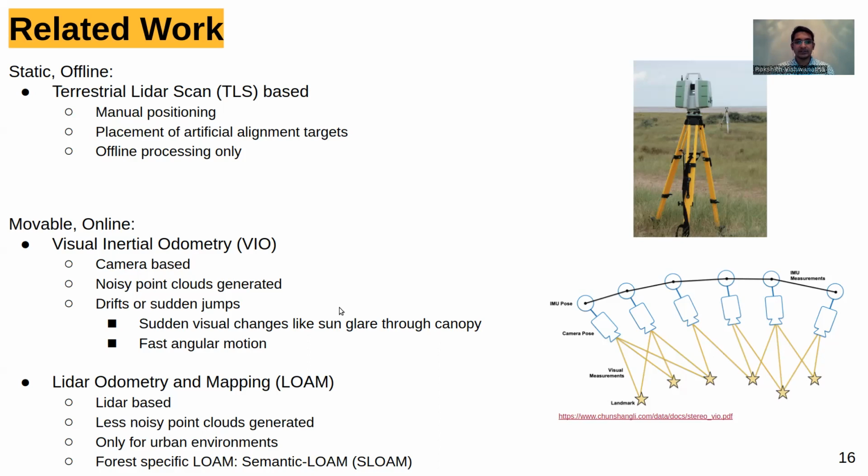So the visual inertial odometry, I think, has become a very mature algorithm at this point. When you consider the RealSense, it hardly uses any power, and it does all the VIO processing inbuilt, and it's a really tiny package. So comparing LiDAR-based processing with visual inertial odometry at this point in time may not be a fair comparison, just because of the level of optimization that's happened on the VIO algorithms and how they've been able to embed those algorithms directly onto embedded systems and low-level processors.